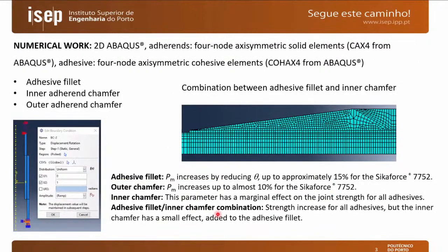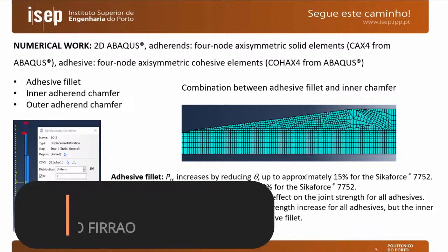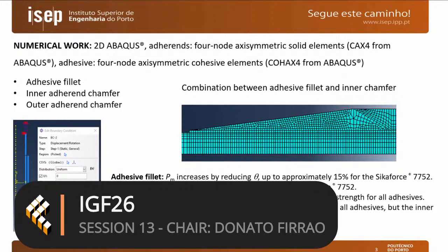In this next and last slide, I give some details about the numerical work. We consider the Abaqus software, which has an embedded formulation for cohesive elements, namely cohesive elements with a triangular damage law, in which after reaching the peak load, we have a linear softening up to failure of the CZM elements. In these models, of which I have an example here in this figure of the meshing process, we consider